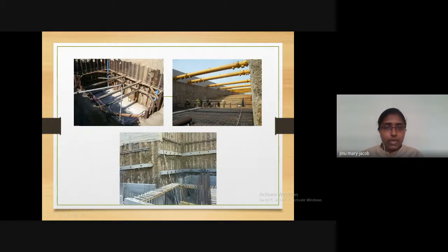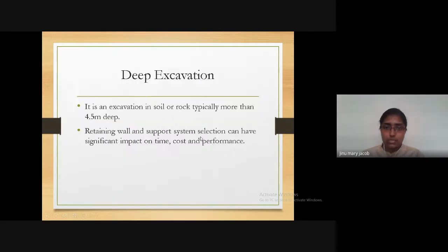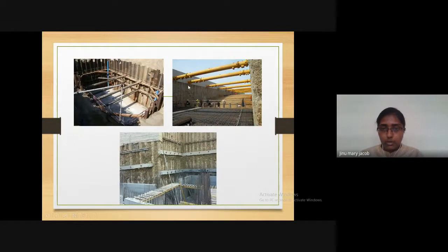Okay, and these are some photographs of some deep excavation works. Here what we see is a sheet pile shoring system with struts and walers. And here it is a secant pile system with struts. And this is another type of wall, contiguous wall with anchors. Here, if you see, we don't have struts. So it is having back anchors which go into the soil and take the load. All such things we can model using Plaxis because we need to design what is the pile or what section of sheet pile is required to take it